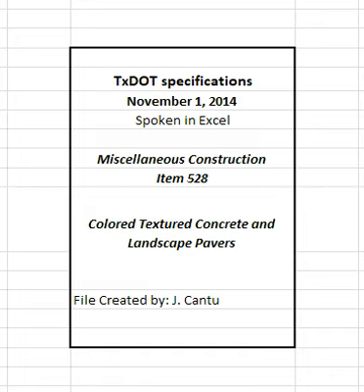3.2.1 Removing and relaying existing pavers. Exercise care when removing existing pavers, making an effort to remove the pavers with minimal damage. Removal by mechanical means is allowed unless otherwise shown on the plans. Ensure that any removed pavers remain in good, reusable condition. Dispose of stained or damaged pavers.